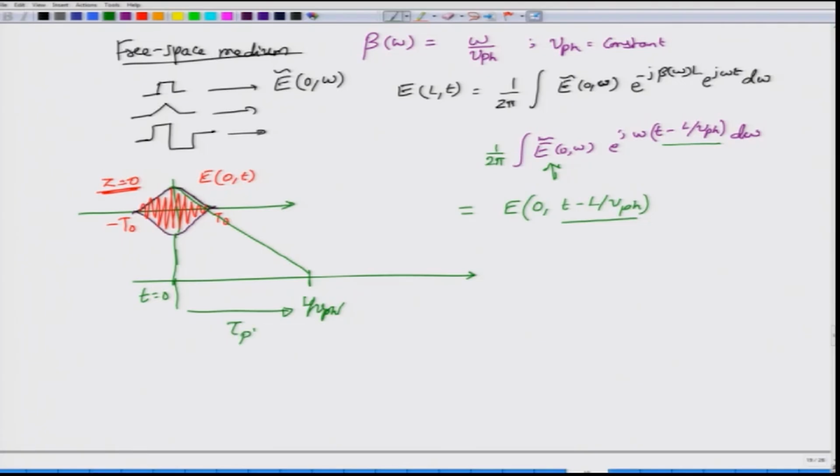and this delay is what we call the phase delay. Luckily, every frequency component that makes up the pulse will experience the same delay, and therefore arrive at the output at the same time. That is, the entire pulse would arrive without any change in the shape.